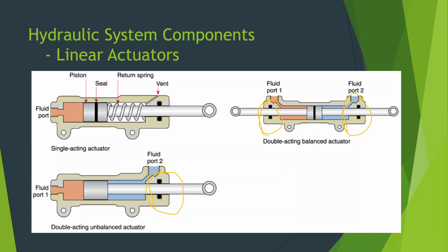That's because phosphate ester fluids, Skydrol fluids, are really good at stripping paint from aluminum. They almost always had some paint missing unless they had just come from paint. It doesn't take long for them to start bubbling away from that little bit of fluid that comes from those actuators.